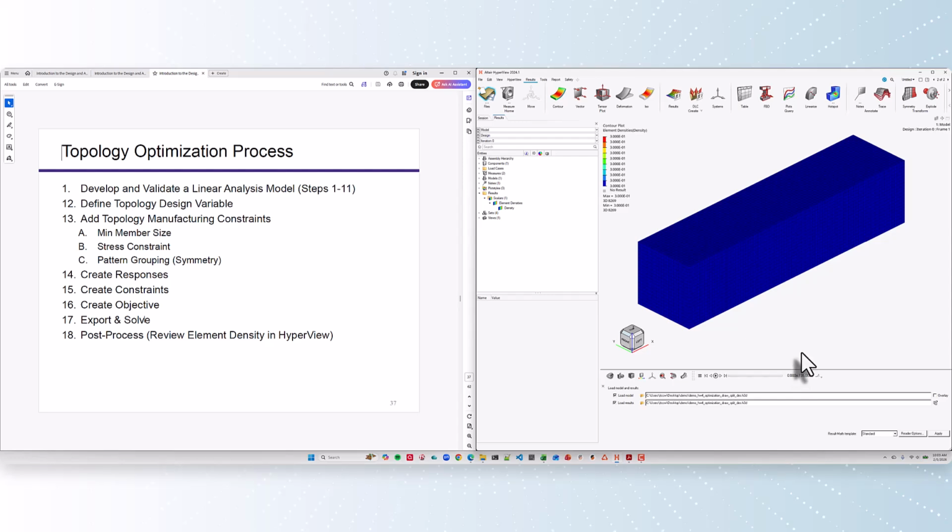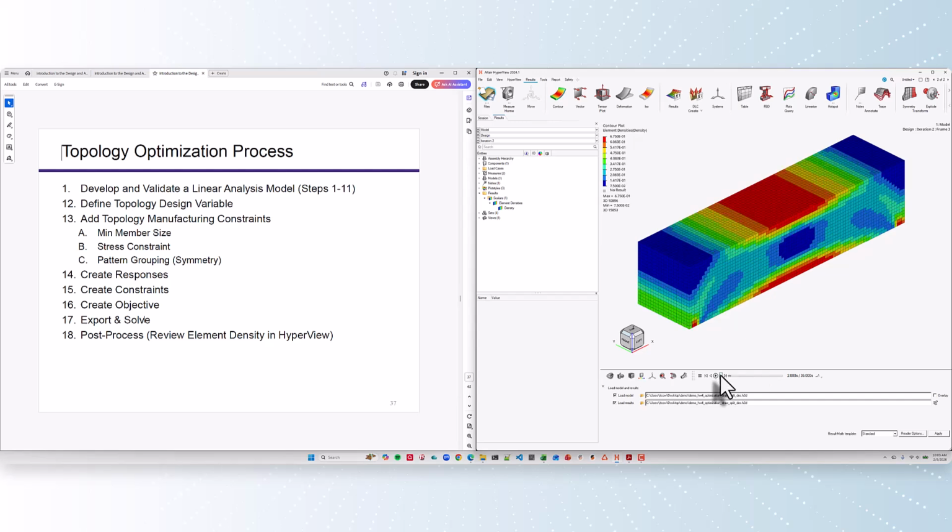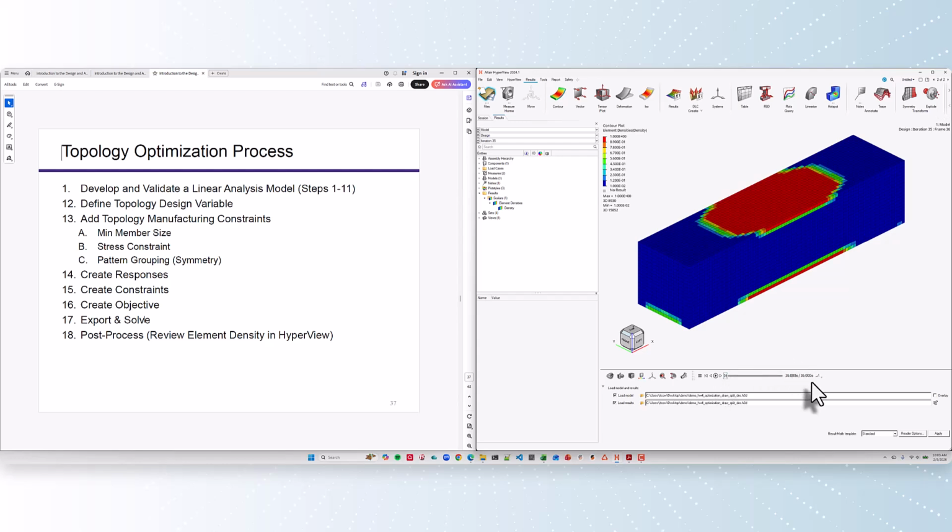So when you go into the transient mode, you can then use these buttons to go through. Here's iteration 1, iteration 2, iteration 3, 4, 5, and so on. I could use the fast forward button to go to the very last iteration, which is iteration 35. That's the one where it converged on. That was my last number on that curve. So you should pay attention to the total number of iterations. I had forgot to mention that. In this case, it was 35.